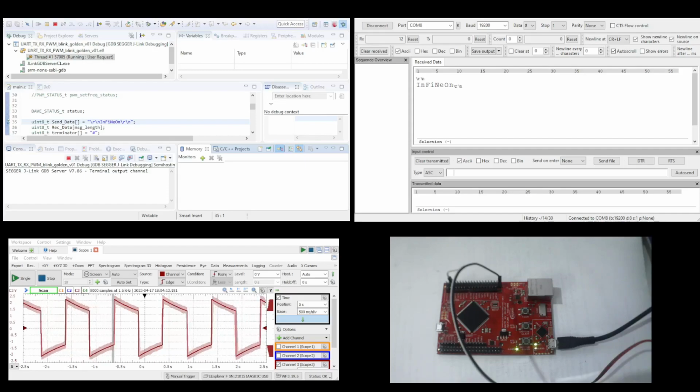When a signal is on half of the time and off half of the time, the digital signal has a duty cycle of 50% and resembles a square wave. When the digital signal spends most of the time on rather than off, it has a duty cycle of more than 50%. When a digital signal spends most of the time in the off state rather than the on state, it has a duty cycle of less than 50%.